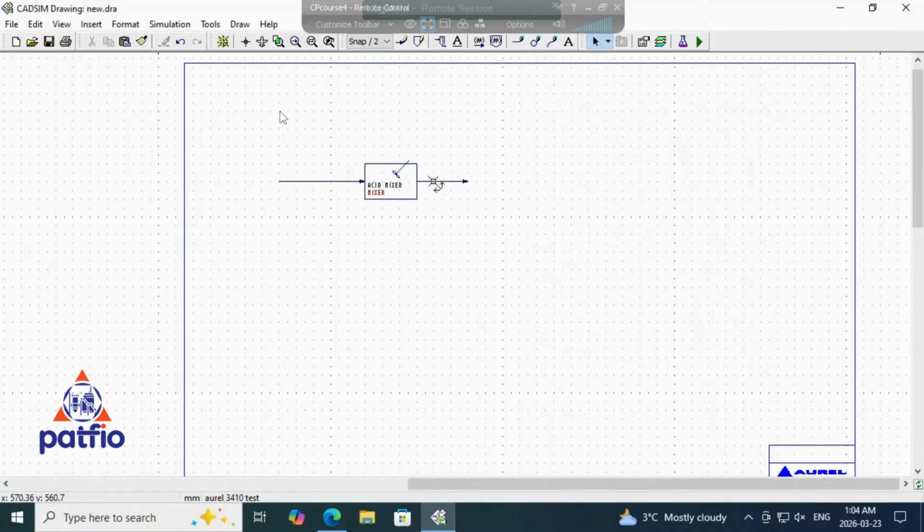I'm going to left click this part so that my cursor comes here. Then I come to this part here, draw process line. Click here. Now I have a line from here, so I want my line to come there. I click here, go down onto the mixer. Right, I click the escape key. So now I have two streams.